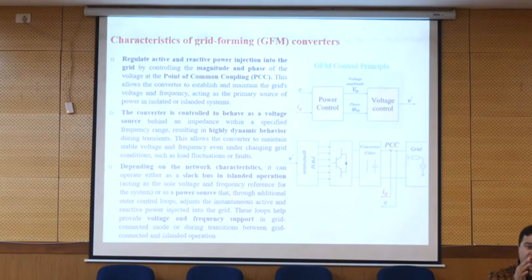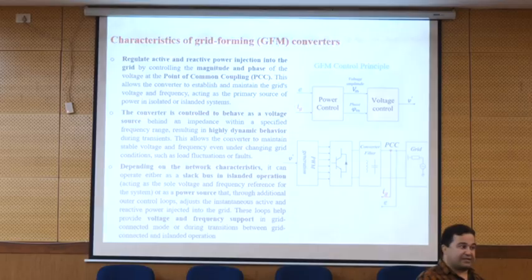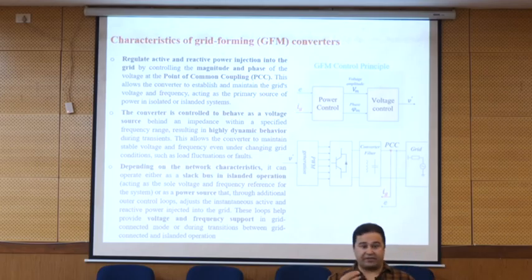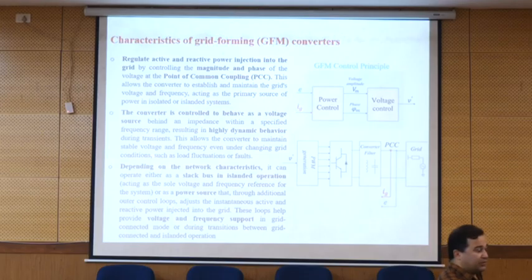So it is good to follow the grid. This is why, when we have multiple systems, it is better that we have synchronization with the grid. There are some other technologies that you can be synchronized with the grid without using the PLL, but the best is that we have a reference from that. Any question?